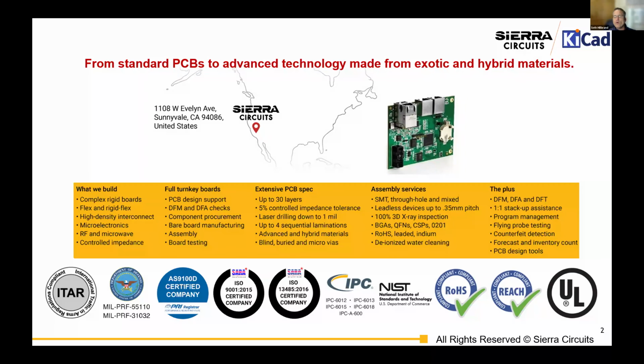However, when you are, for example, placing a silkscreen item that violates the clearance to the edge of the board, for instance, if you have a DRC custom rule that specifies silkscreen offset from the board edge, that is not going to be real time. That will be something that is caught by the DRC check and highlighted to you as part of your design process. Got it. Okay. All right, great.